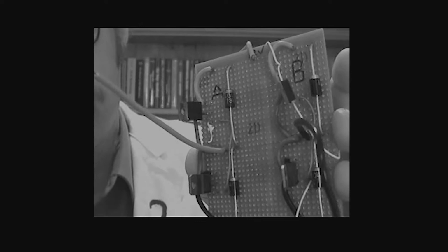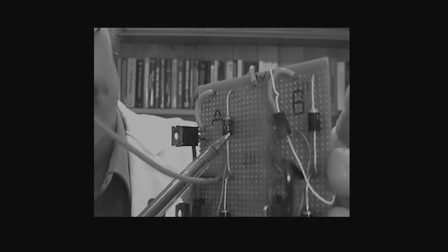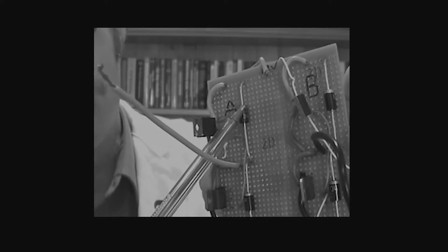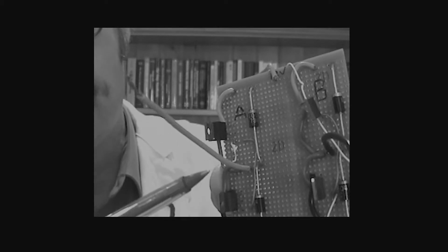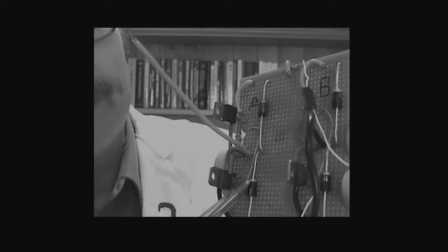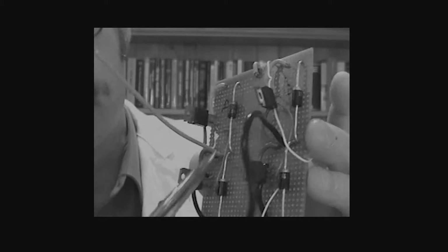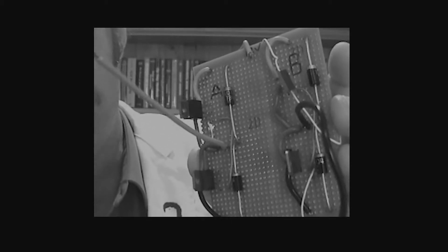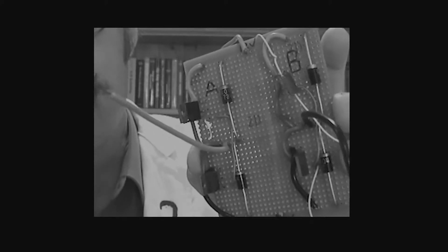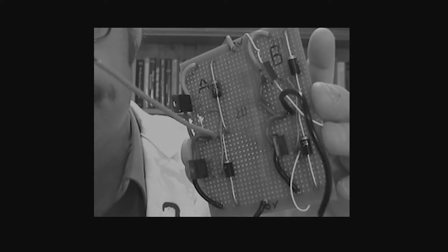this DC motor. If you notice, we actually have diodes in this circuit. We have a diode here which is connecting to this lead here that goes to the motor. And then we have a diode here that's connecting to that lead, and on the other side we have a similar sort of thing. So we have this diode here and this diode here. Now these diodes are really used to protect the transistors. So this is an application where we're using diodes for protection.